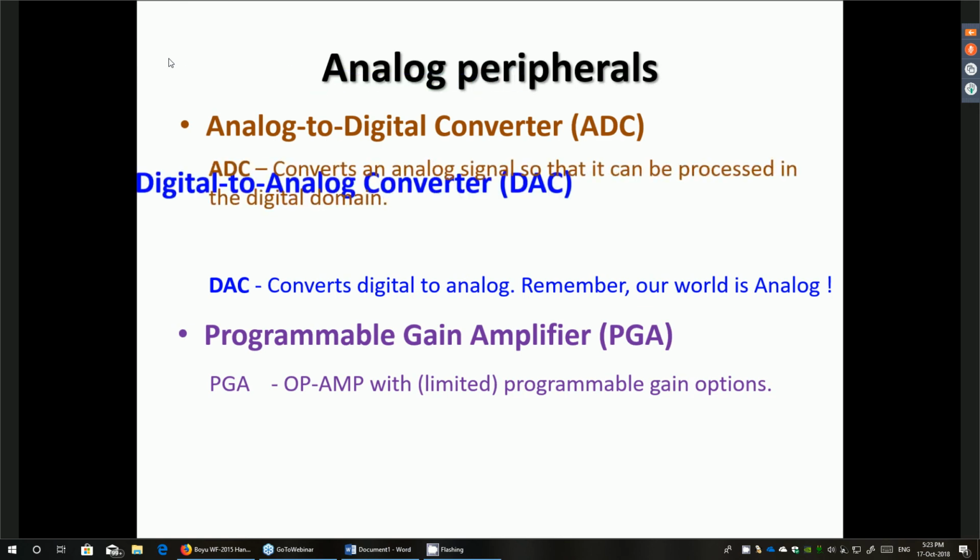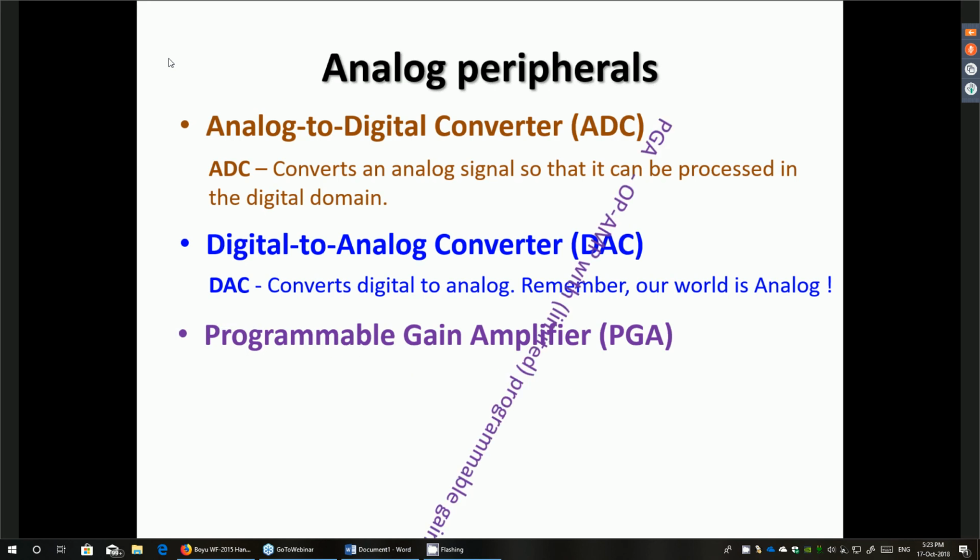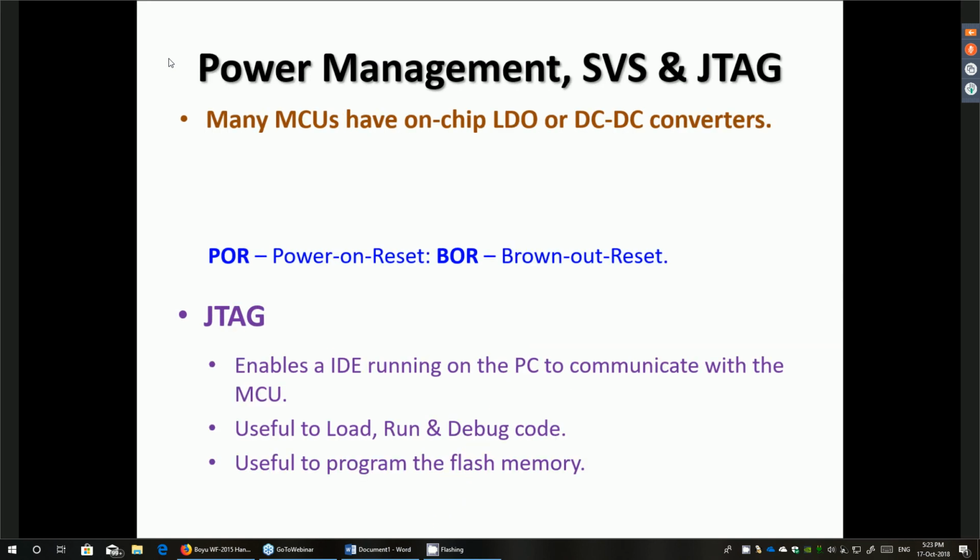So we have looked at some of the peripherals that a designer of an embedded system needs to consider before choosing the right microcontroller. And there is also other support circuitry like power management. When I showed you the image of the system in package, or even the SOM, system on module, you saw two ICs, PMIC, power management IC. You saw LDO, low dropout regulators.